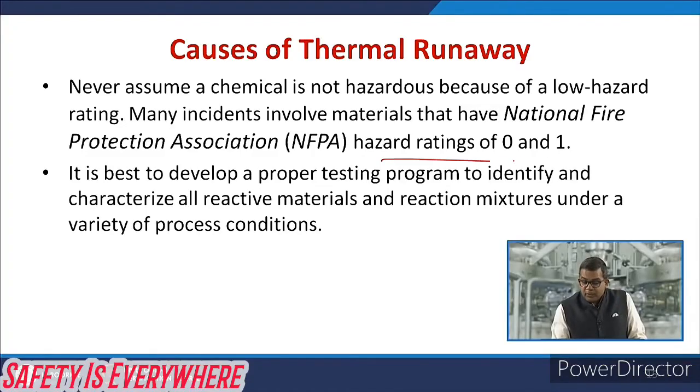That is very much needed, because in Bhopal, it was thought unlikely that water would meet MIC. These are very reactive, the reaction is exothermic in nature, and the system was not designed at all to cater to this type of scenario. So if you have a hazard rating between 0 and 1, don't think that this particular system is safe. You have to take proper measures to safeguard the system.